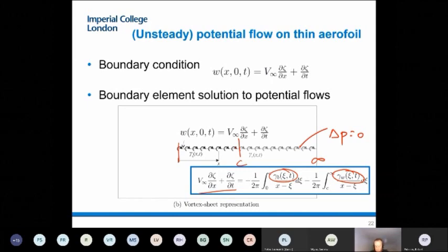And that one requires a bit more thinking because we still don't have a way to link velocities and pressures. For that, one thing I should say is that if the flow is assumed to be quasi-steady, which means stationary flows on airfoils, the circulation on the wake goes to 0, and then we don't need to do anything. But we are concerned about situations in which things are moving, and that means we actually need to solve simultaneously for the bound vorticity, that's the B there, and the wake vorticity, that's the gamma W.